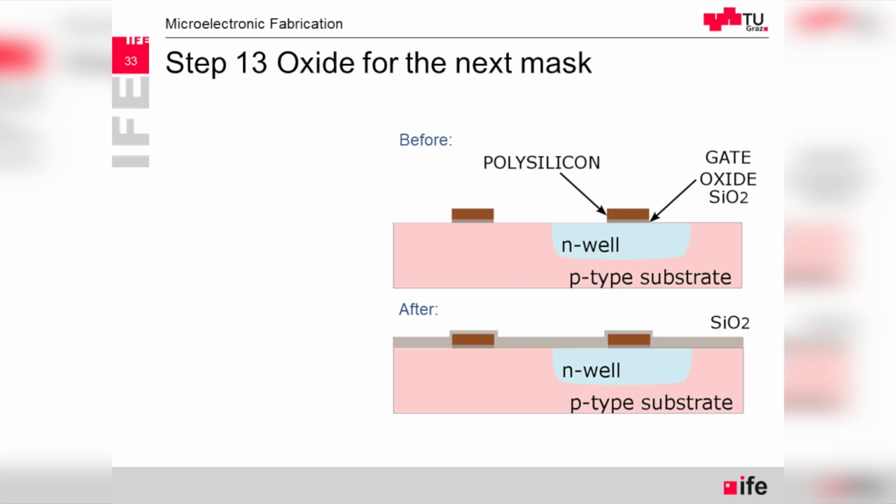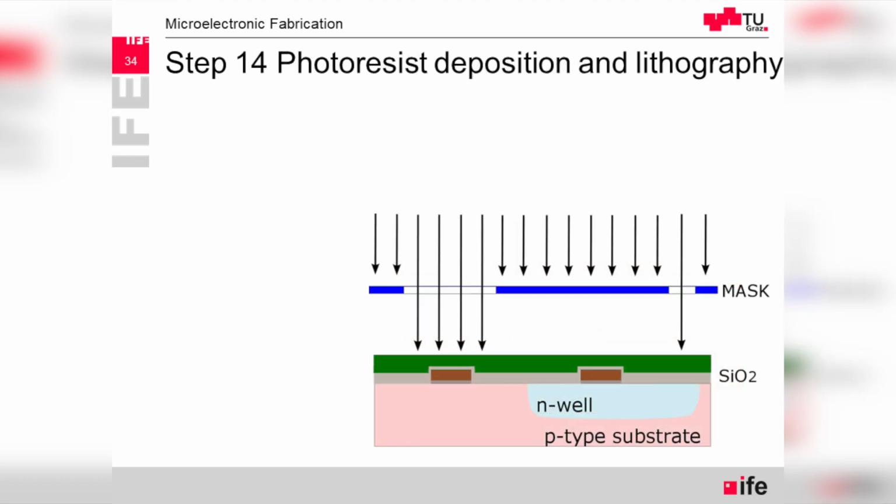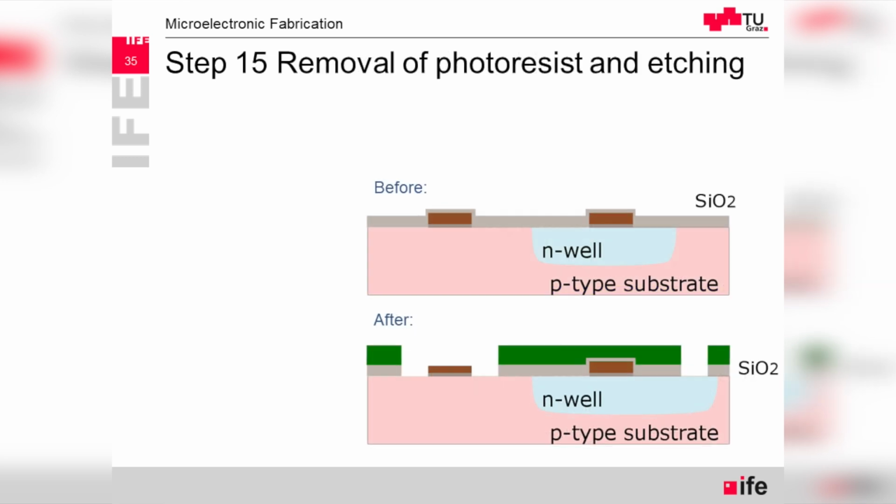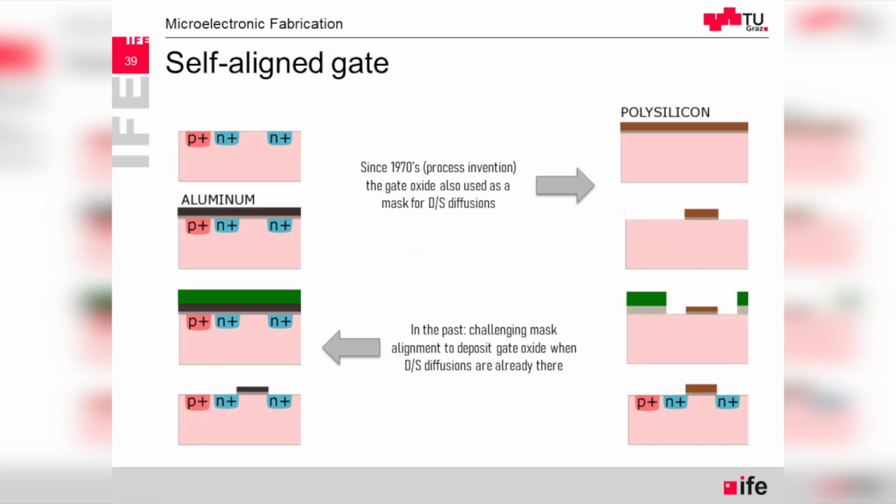So in terms of defining very accurate length of the transistor, it's much better because we have this self-aligned process. So originally, maybe that was done that way, that we had first the implants, what you can see on the right-hand side, then there was deposition of the silicon dioxide, and then the gate conductor, which used to be aluminum, low temperature process.